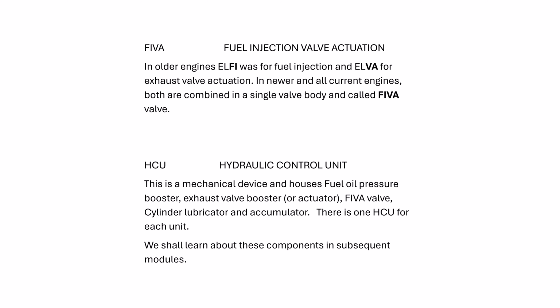Fuel injection valve actuation. In the older engine, LP was the fuel injection, as I just told you, and ELVA was for exhaust. Later on, they combined these and made one, FIVA, fuel injection valve actuation. That's how they took the nomenclature, FIVA. Now, the SU is a mechanical device and houses the fuel pressure booster, the exhaust valve booster or actuator, the FIVA valve, the cylinder lubricator, and the accumulator.